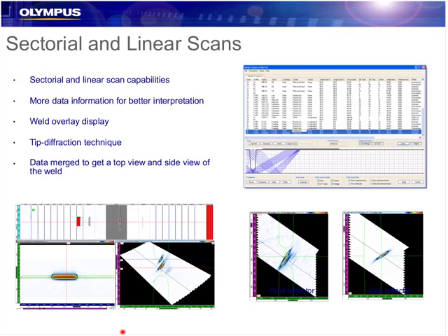So here we see views, if you've used an OmniScan or Focus LT, more accustomed to what you might be used to looking at. So we have a C-scan as well as an S-scan with a weld overlay of the joint, and again a linear scan with the weld overlay as well. So often these are used for extra information or added information to be able to discern geometric reflectors or do some tip diffraction sizing. So the zones are very good, but having this added benefit in some cases, the ability to add sector scans and electronic scans selectively, can be very good for certain joint designs.